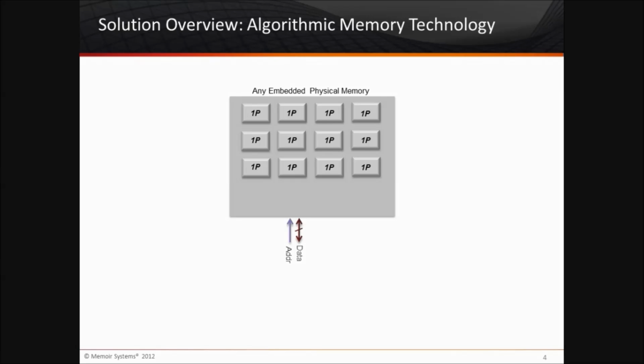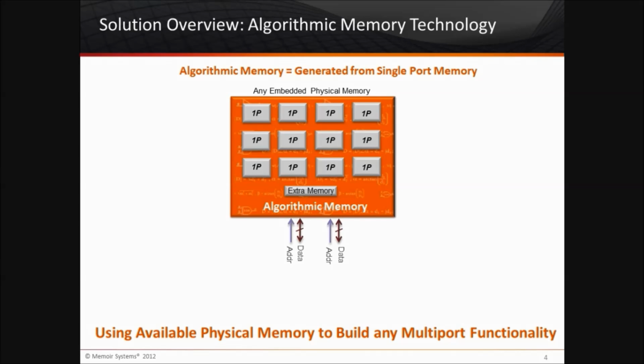What we do is we try to solve this problem by giving you more accesses in the same clock cycle. And that is shown in this animation here. We add an orange block, and that's RTL. Hopefully it doesn't scare you, because we're not adding that much RTL. It's just a little bit. And this orange block also embeds a little bit of extra memory, which is hidden and not seen by the external user. What we've drawn here now is a dual port memory that's been given to the architect or the designer. So you get 2 ports. Each port is bidirectional in this example, and you can fire away both ports at the same time. Notice that even though the physical memory can only support 1 access per clock cycle, we're going to allow 2 accesses from this external interface.